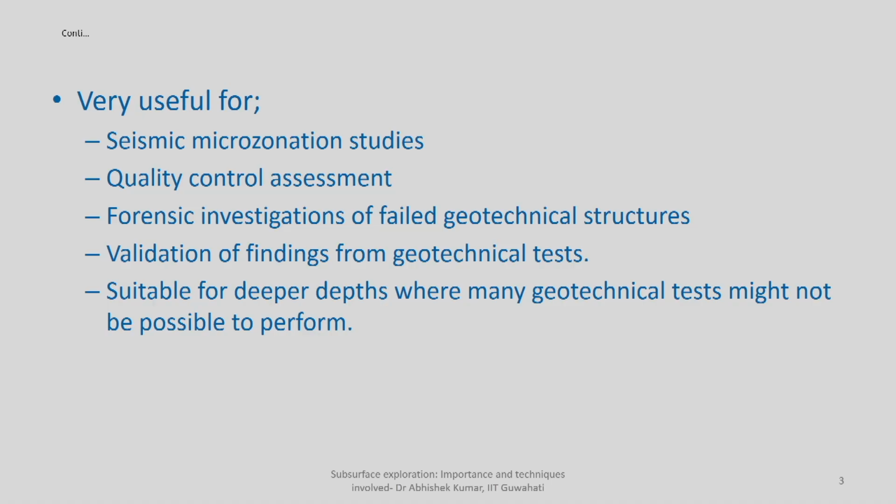Further, those ground motions will be altered because of the presence of local soil. So, in order to take into account the variation in local soil properties at your site of interest over which your building is located, geophysical tests are more and more nowadays being practiced, so that you can quantify the subsoil properties. Once you know the subsoil properties, you will be able to identify how these subsoil properties are dominating in controlling the seismic vibrations in a building.